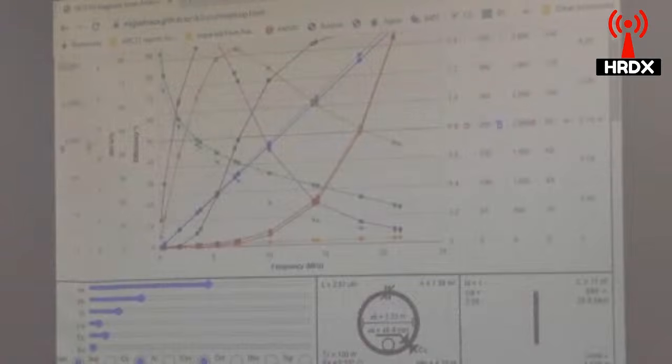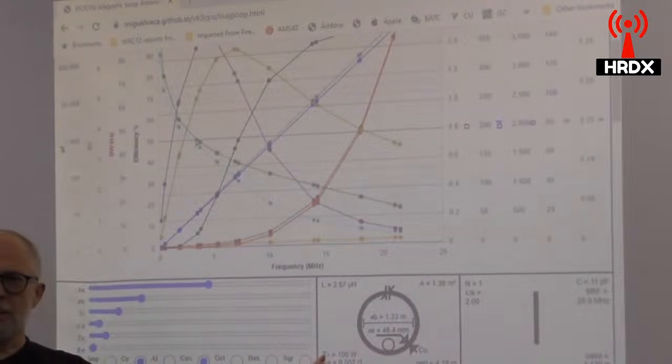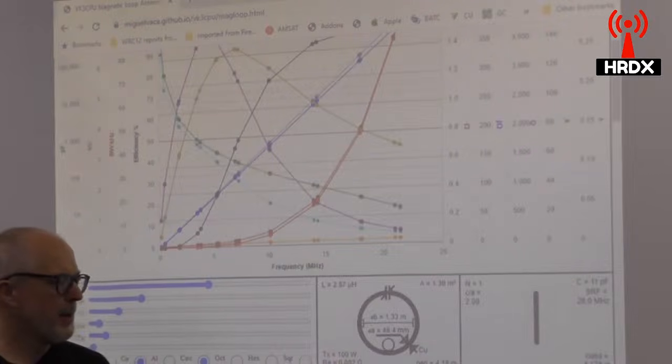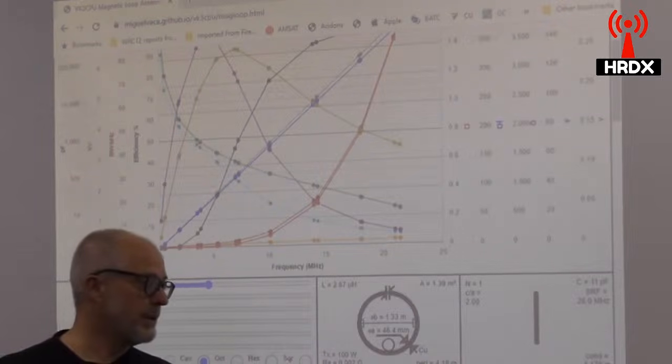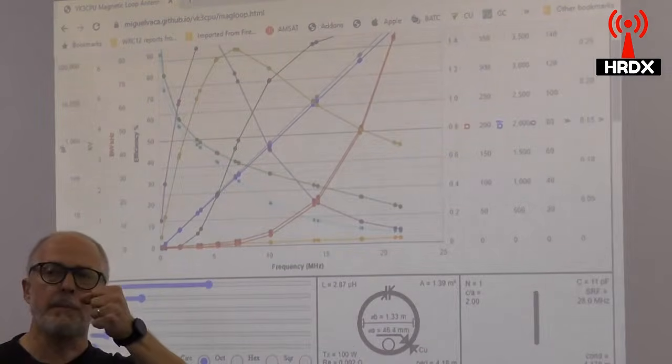Now, I was able to get, through silver soldering, and I'm using 46% silver solder, which is the most silver that you can get. I was able to silver solder onto the ends of the bit of coax, and I'll show you that in a sec. The plates then connect to the vacuum capacitor, and on measuring it using Alan's wonderful 4-wire resistance meter, I was actually able to get down to 0.0023 of an ohm between one connection to the vacuum capacitor and the other.